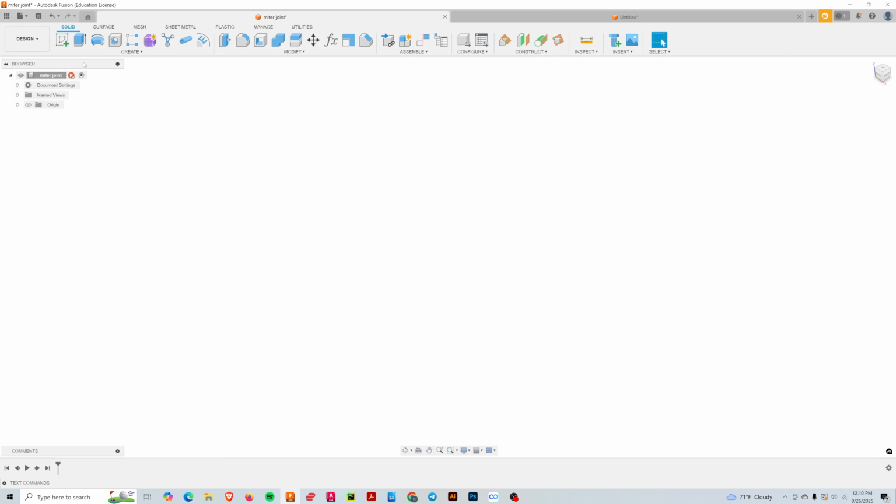So I'm going to press sketch. We're mostly always going to start with the sketch. Be aware of where you are, and let's say this is top, this is the front. I'm going to choose, I'm going to call it the left side. You can call it the ZY axis plane, but in any case here. And if you can't see this, you can just turn on the origin point. This is the origin point. So I'm going to click on this one because I'm going to extrude to the right.